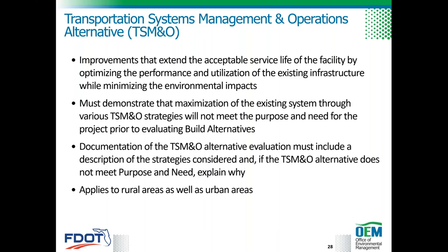Prior to evaluating build alternatives, engineering analysis must demonstrate that maximizing the existing transportation system through various TSM&O strategies will not meet the purpose and need for the project. While TSM&O primarily relates to projects in urbanized areas, the concept of achieving maximum utilization is also important in rural areas.